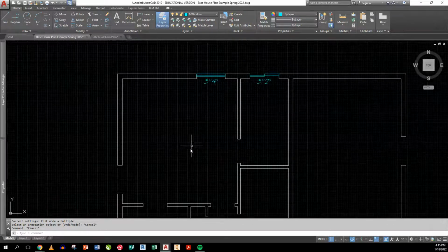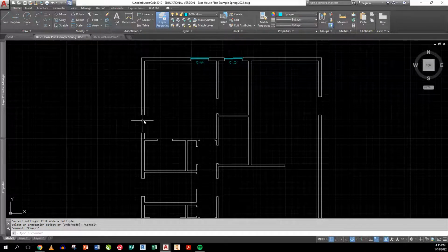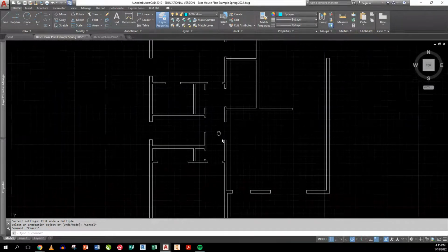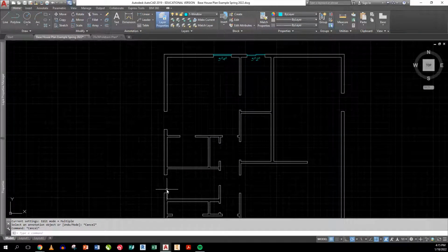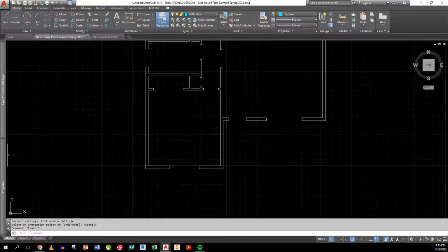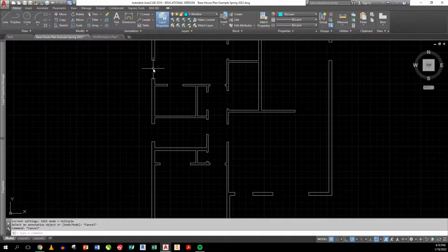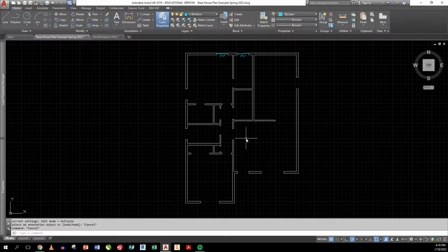Now I'll go back through in my plans and I'll draw in all the rest of the windows the same way. I'll draw this in because it's the exact same as this. Put it right there. These down here, this one's, I believe, the same window as this one, so I could actually copy it and rotate it and put it right there. These down here, I've got a front window here that's a 6050, I think. Yeah, it's a big picture window. And this is a 5040 window, okay? And both of these would be horizontal sliding windows, unless they're picture windows, which is just a pane of glass. So it's horizontal slider, vertical, single, double, okay? So I just drop those in as we go. Now, that's it. We'll come back and do doors in just a minute.